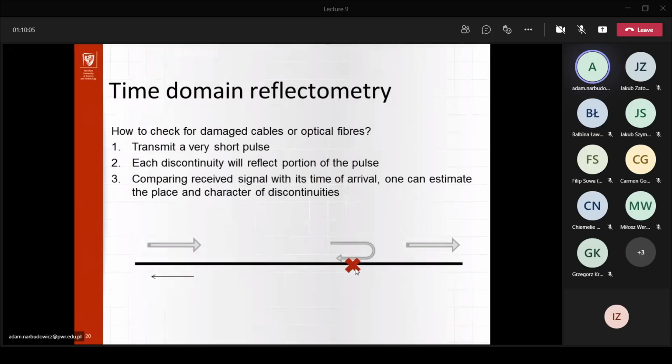Okay, so at which point your cable is broken. So that's basically a smart way of dealing with broken cables. It's pretty much the very same principle as you would see with a radar. The difference, of course, is that it's easier here because you're propagating your signal through a cable and not through an open boundary of a radio signal.